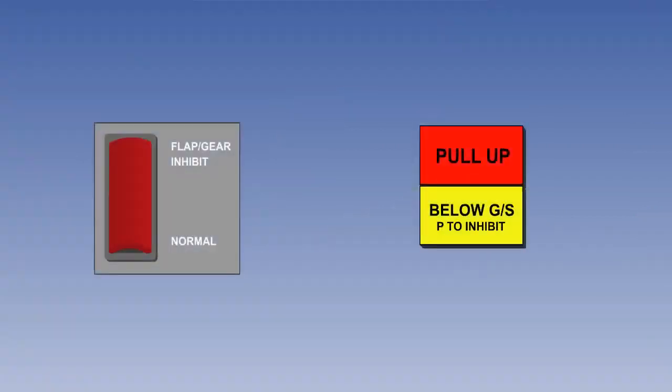The two times when the GPWS, eGPWS would need to be inhibited occur during the approach phase. These are either if the flap gear positions are known to be non-standard, or if the crew are flying an approach without regard to the glide slope.